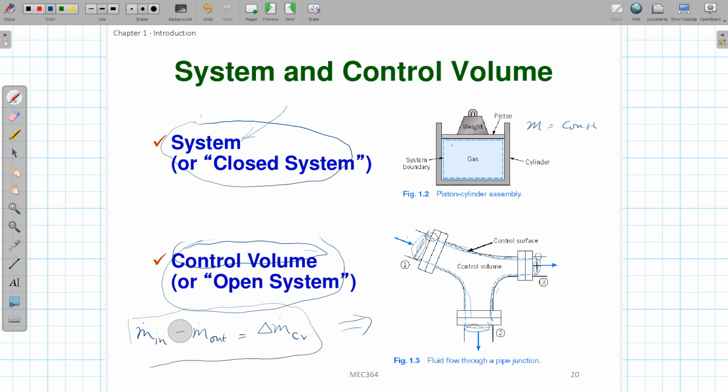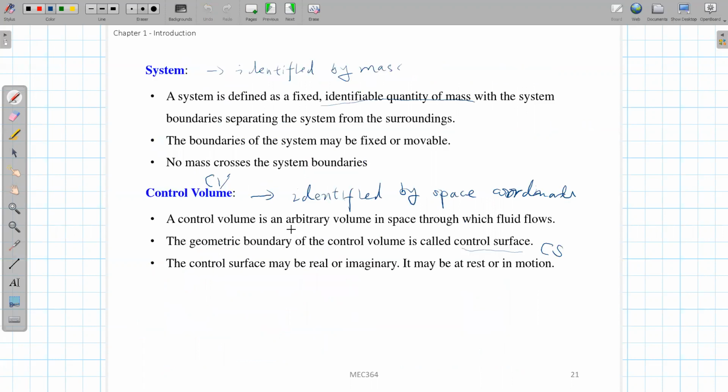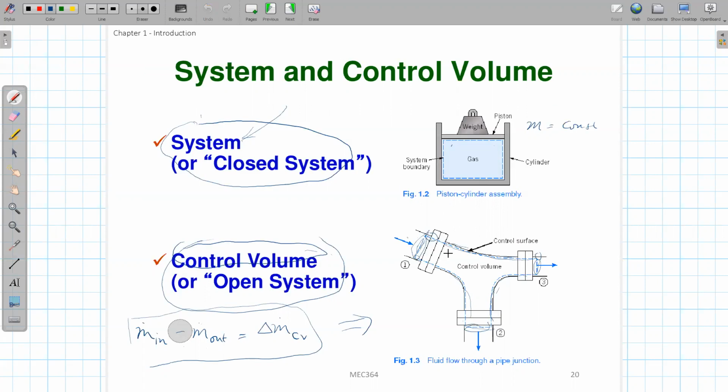Not necessary, because as we already mentioned, the control volume can be an arbitrary volume. You can define the control volume in any way. In this case, I can even define the control volume just here. I can just define this part as a control volume. It doesn't matter to me. And in this case, all these 4 boundaries will become imaginary. This will not be a physical control volume. And I can also apply the mass conservation and momentum conservation on this control volume here.